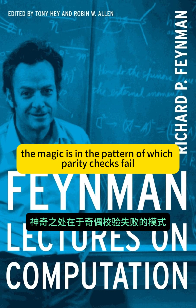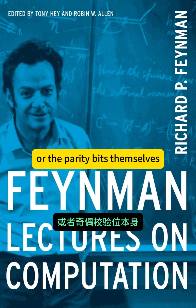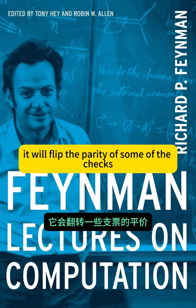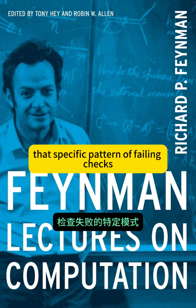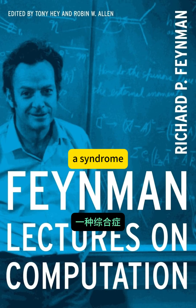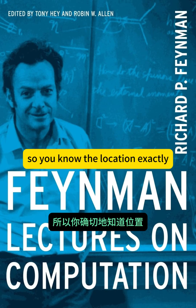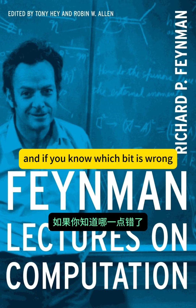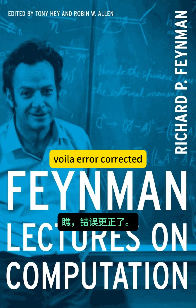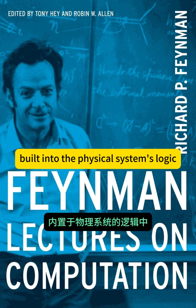The magic is in the pattern of which parity checks fail. If there's a single bit error somewhere in the data, or the parity bits themselves, it will flip the parity of some of the checks, but not others. That specific pattern of failing checks acts like a code, a syndrome, that uniquely identifies exactly which bit flipped. So you know the location. Exactly. And if you know which bit is wrong, you just flip it back. Voila, error corrected. It's automatic error correction built into the physical system's logic.